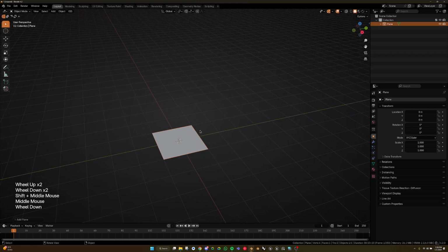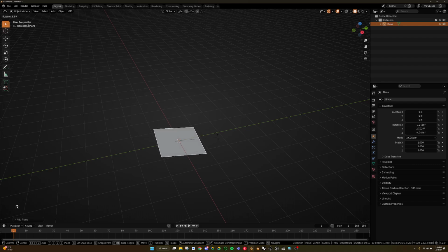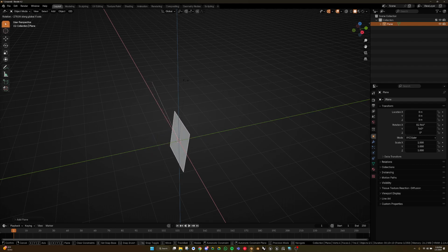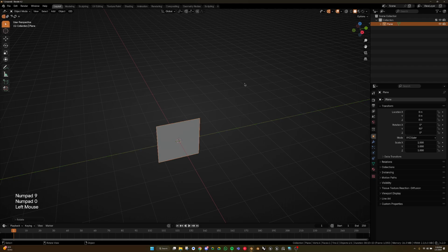Then I'm going to rotate this. I'm going to press R to rotate, and I'm going to rotate it along the green axis, which is up here. You can see it's Y. So R to rotate, and you can press Y on the keyboard, but I like to do things really fast. So when I press R, I hold in the scroll wheel, and you see this white line. What you want to do is align this white line to the axis you want to rotate on. You align it, and it locks to that axis. So I want it to align to this one, so I let go, and then I can rotate it. And then I can type a value of 90, like that.